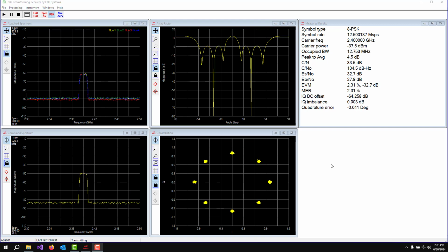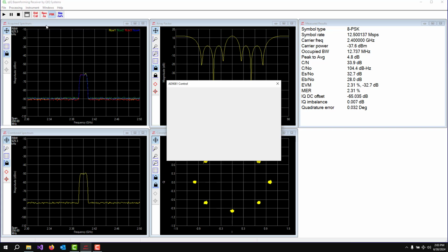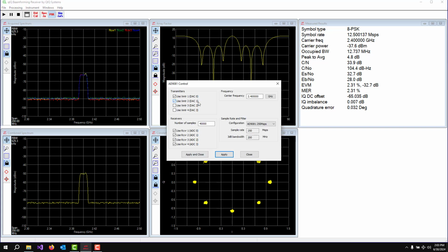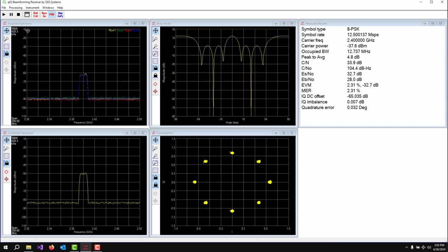Another benefit of using antenna arrays is this array factor, this pattern that receives energy in some directions and rejects energy coming from other directions. So let's do an example to see what that looks like. Let's go up here and turn on our antenna at 30 degrees off boresight. That's that two-tone signal that we're thinking of as interference or jamming.